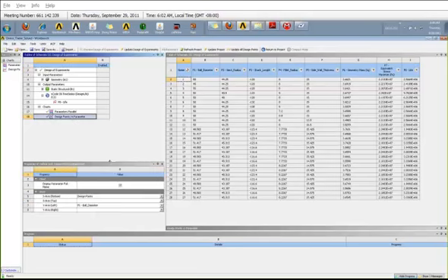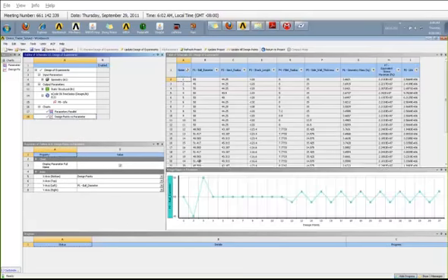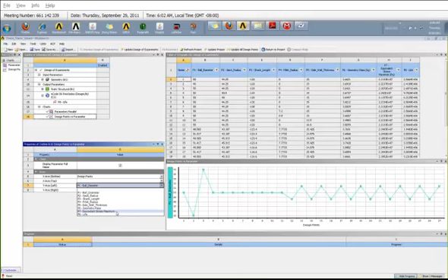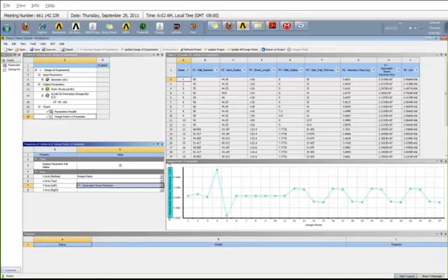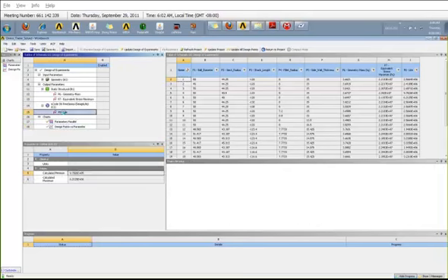And in this one also, I can display graphs of each individual input or output parameter based on each of these design points. So in this case, I can plot how my maximum stress changes based on these design points. One thing that I forgot to mention is, as an output parameter, I have DesignLife from my nCode DesignLife. Also, I have parameters from my static structural where I'm looking at the weight of the part and also the maximum stress of the part.